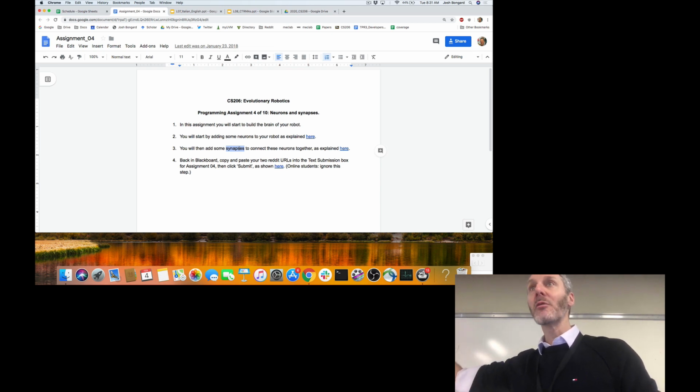So the values come from the motor neurons to the motors, where they're interpreted as torques. Torques are applied to the objects. The physics engine takes over, computes the new positions and orientations of the objects, which causes changes to the sensor values, and around we go. So when you finish part 2 of assignment 4 this week, you will see your robot actively acting in the environment. And at that point, you can start modifying one or more of the 6 elements that make up the robot.